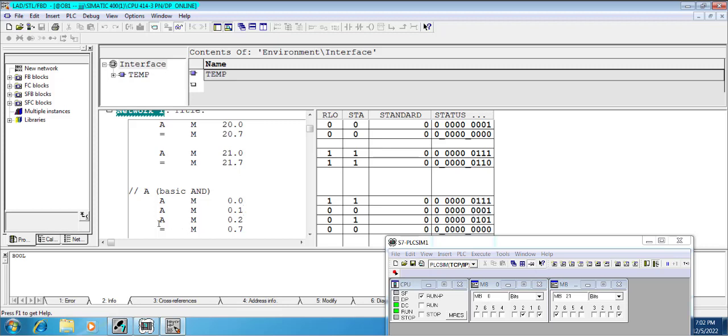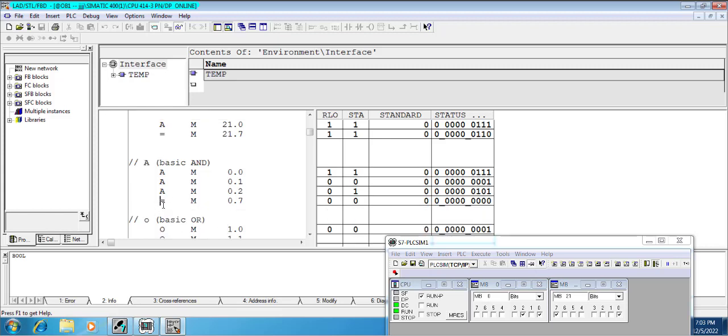Now we come to the third instruction. The value stored in that address is actually 1. This value is reflected by the status bit in the status word register. It checks previously and sees that the first check bit was 1 and the OR bit was 0, and therefore it needs to combine the current value with the previous value of the RLO, which means that 1 is combined with 0, yielding 0. Then the assignment structure comes to end that block,